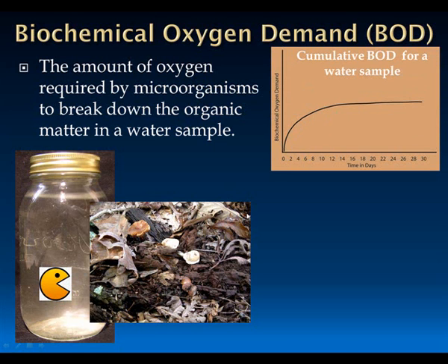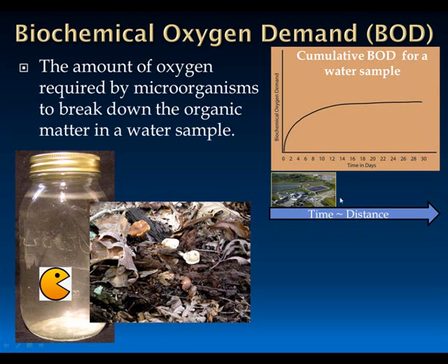And a lot of the stuff is really readily broken down, and you might have heard of a 5-day BOD, and that's because at 5 days you've broken down the vast majority of the material, and then the rest of it is really slow, and so this line flattens out, and there's less oxygen demand after 5 days.